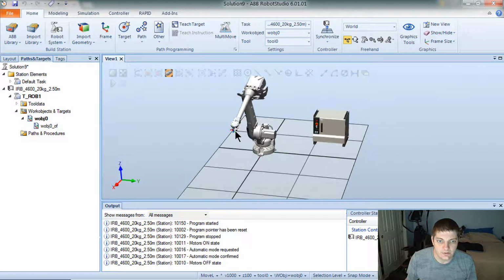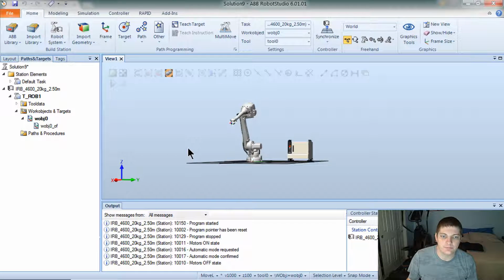If you think about what a point in this system is going to be referenced to, the base of the robot makes a pretty good default location. And really it doesn't matter a lot of times, because as long as the robot's repeatable to those points that you teach, then it should be okay. You don't often care exactly about the numbers; you more care about their relationship to other coordinate frames, or to the robot itself, or to the part. We'll get into some of that calibration stuff later.